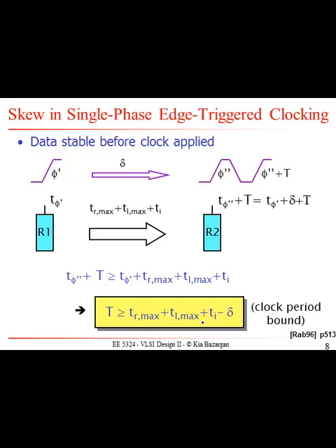And if you think about the maximum bound on delta, essentially what you want is to have the data fetched in this clock cycle. So let's say right now you're not worried about the fastest arriving value to the inputs of R2, but you're worried about the most significant bits of your adder, for example.